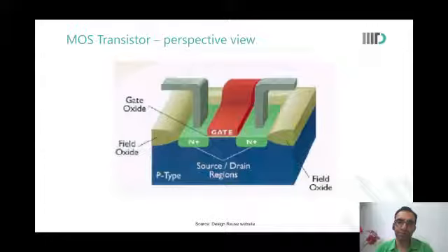The depletion capacitance when there is an inversion. Yeah, depletion capacitances, Gagandeep also mentioned that the source and drains will have their junctions and that junction would lead to capacitance. That is what you're talking about? Yeah, so gate to substrate capacitance we said is the same as the MOS capacitance that we've already discussed at length.